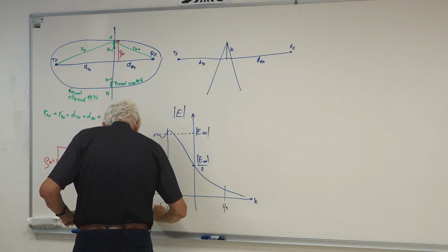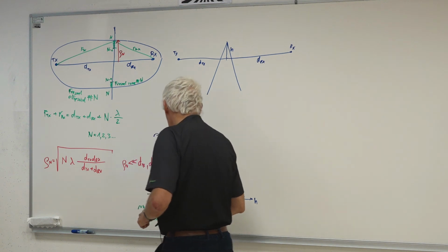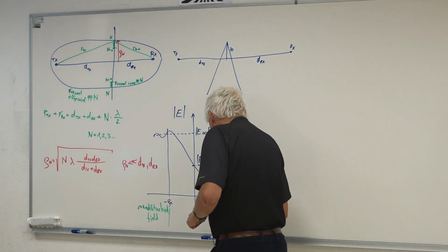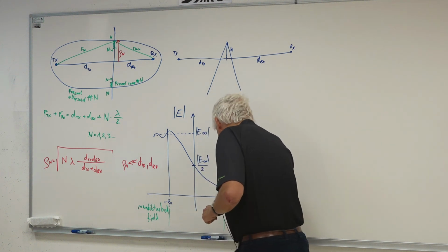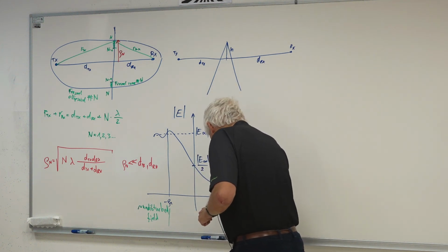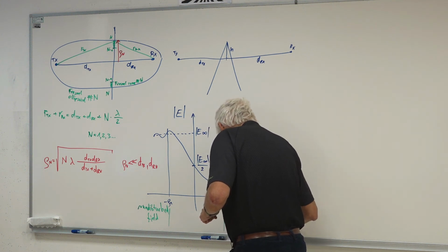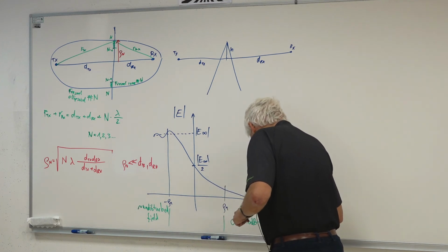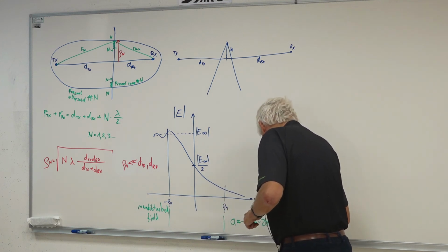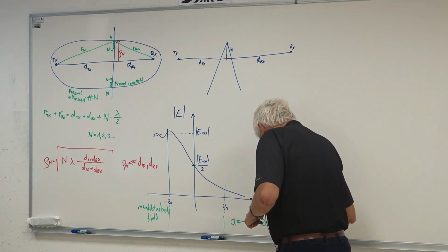Undisturbed field in this region here, in this region, undisturbed field. Above here, above rho1, we have an approximation for the attenuation of this obstacle: approximately minus 16 dB, minus 20 dB times logarithm of base 10 of the height of the obstacle divided by rho1.